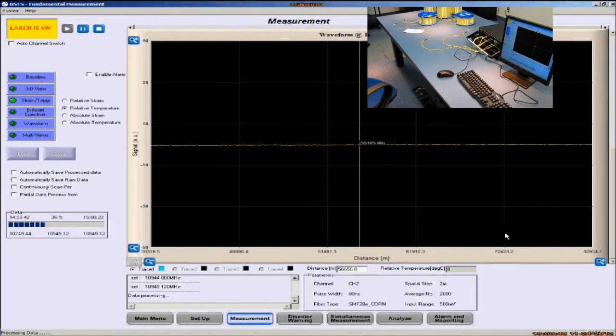So, only a relatively small change in the length, from 120 kilometers to 100 kilometers, allowed us to tighten the pulse width from 200 nanoseconds to 80 nanoseconds in order to generate a good signal that the Brillouin sensor can measure. So this shows just how the relationships are between fiber length and sensing resolution.